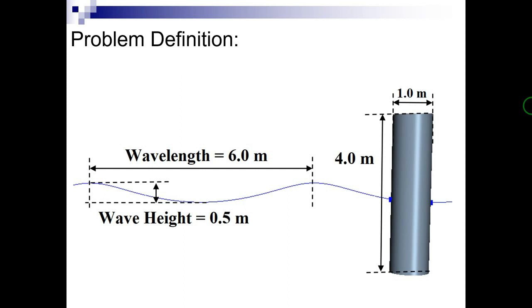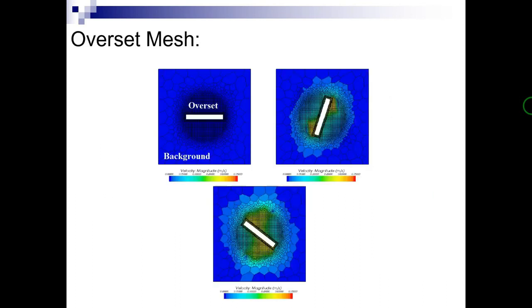To fulfill the main purpose of this tutorial, we're going to use the DFBI technique, which allows us to model the motions of a rigid body due to the applied forces and moments, together with the Overset mesh technique as shown here. The overset mesh, which contains the rigid body, is superimposed over a background mesh which is normally stationary, as shown in this figure. Background and overset mesh region, where the rotational movement of a body is modeled here.